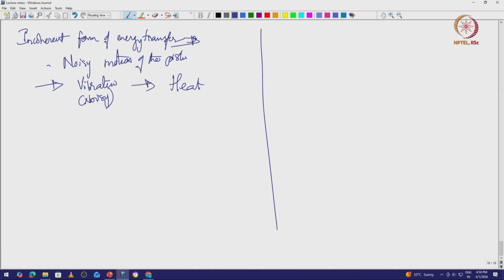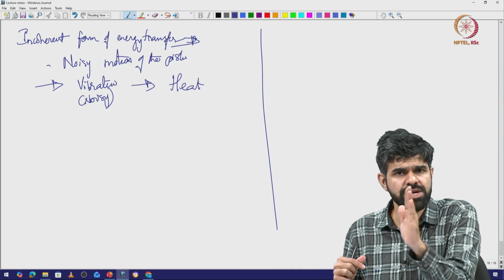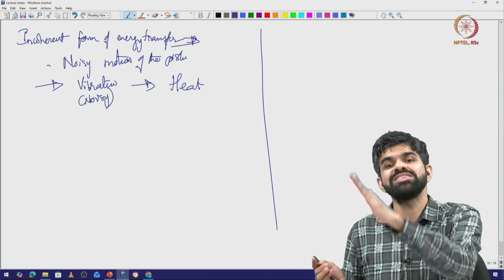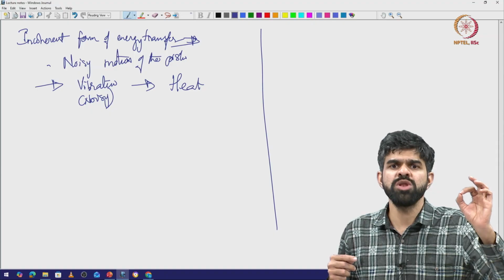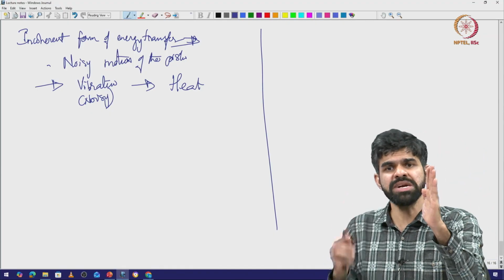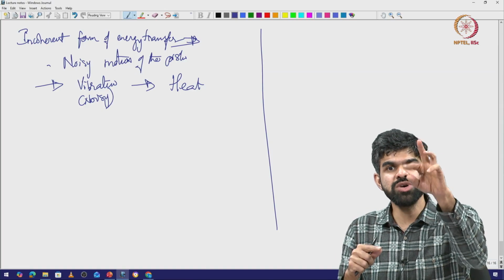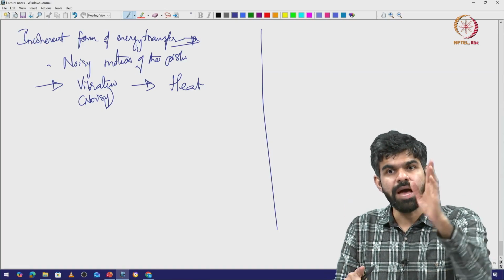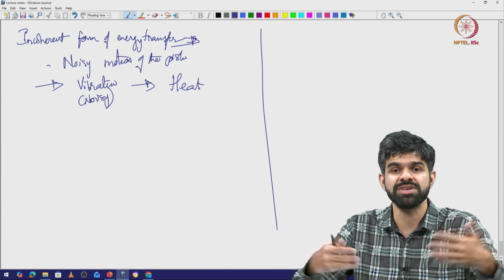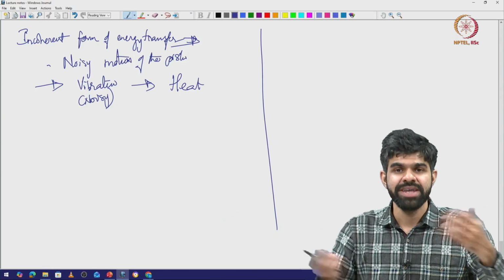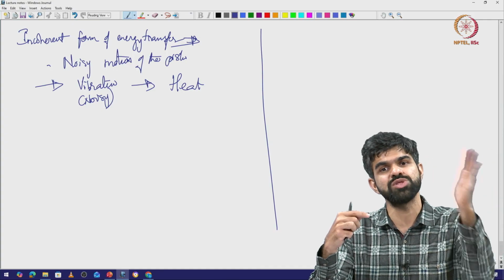The gas is not just transferring energy in the form of coherent work done, right. So, how are you transferring energy from the gas? Every molecule is transferring its energy. Now, every molecule is on an average giving a force F, but there is some variance about F, right. That variance is going to vibrate this piston about the average, and that vibration of the piston is nothing but incoherent energy transfer, and that is why the piston gets heated up or cooled down, depending on the case. So in this case, the heat is being transferred from the gas to the piston, right.